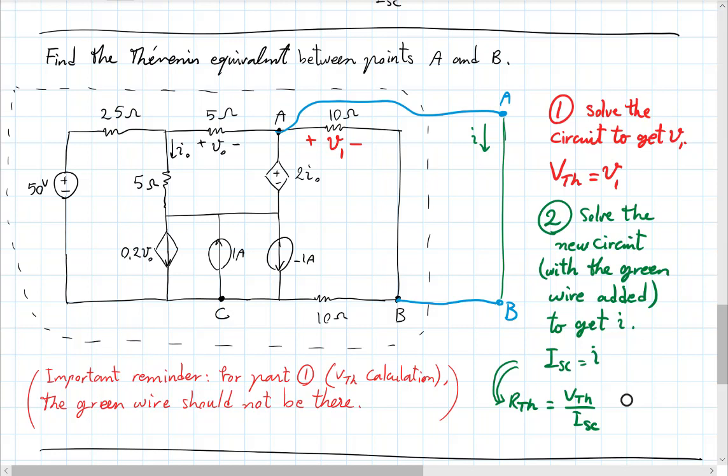Again, you would have to solve the same circuit that you solved in step 1 before. But this time, the voltage of interest is the voltage between points A and C. So that includes the voltage drop, for instance, across this dependent voltage source, 2I0, plus the voltage drop across one of those two current sources. And remember again that a current source could have any voltage that comes out of the solution of the circuit. So you have to have that voltage drop calculated.